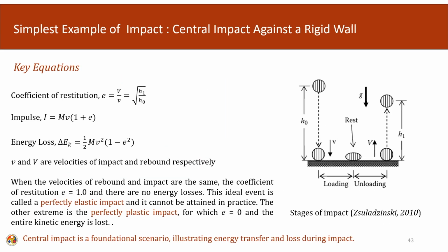The key equations involved in this type of impact are the coefficient of restitution, the impulse, and the loss of energy. When the velocities of rebound and impact are the same, the coefficient of restitution is 1 and there is no energy loss in the system.